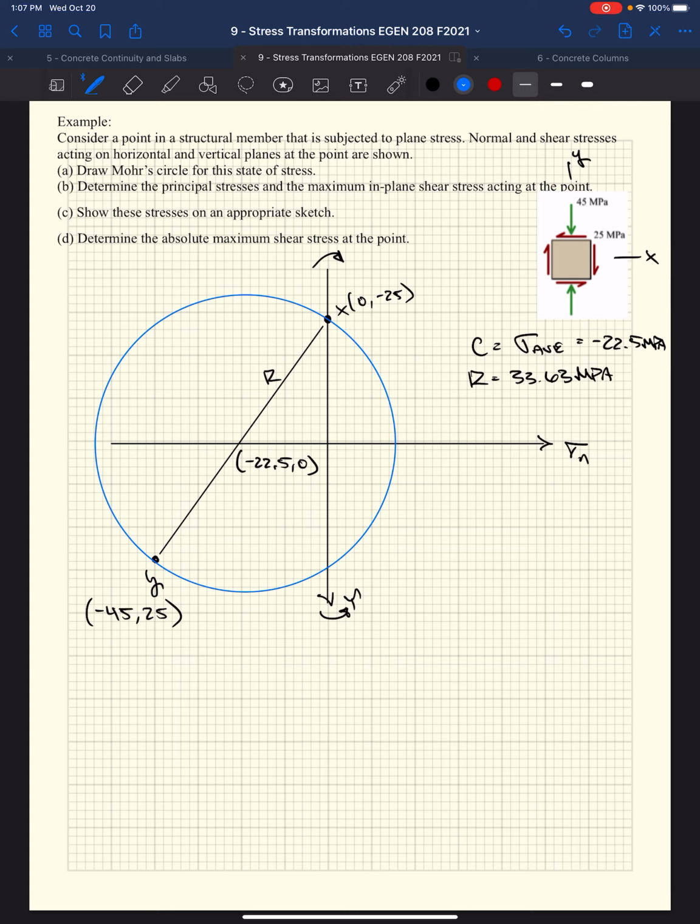The principle that we potentially have this maximum stress that's greater than the stress that we calculate based on, say, normal stress or torsional shear stress, right? That we can cut an element at a different angle than just perpendicular to, say, the axis of a steel rod. And we're going to have stresses that are in larger magnitude, right? But we need to look at that for design to make sure that we're considering all possible orientations of stress within our object to make sure that we capture the maximum stresses that the object's going to see so that we can design our element appropriately, right?